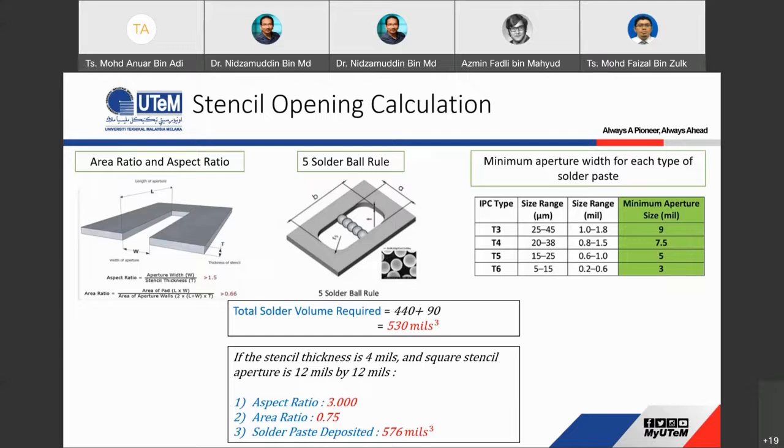When first making a stencil, I usually do it like that. The first design is just like a draft. Then we run one or two boards first, then inspect the result after reflow. If not good, then we need to measure the solder fillet after reflow under a scope.